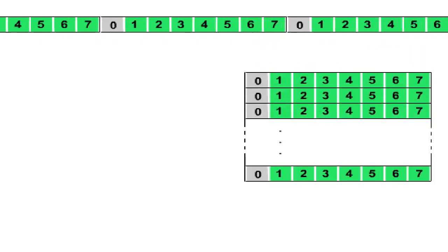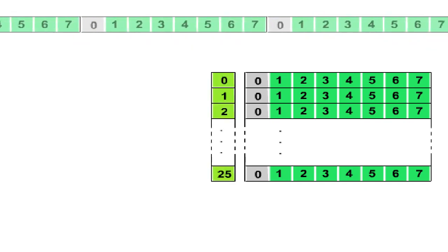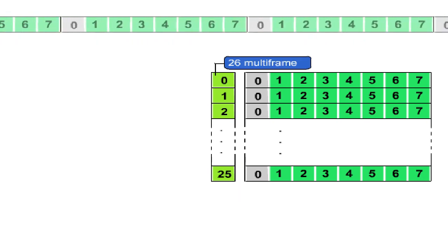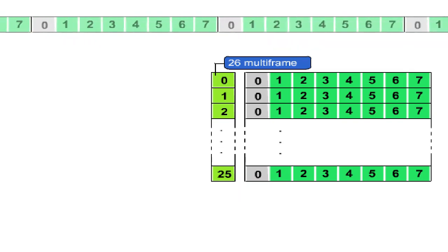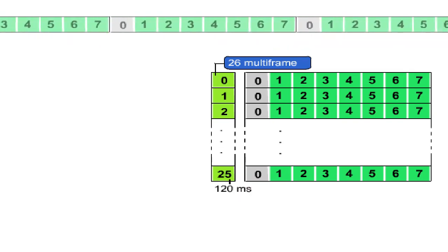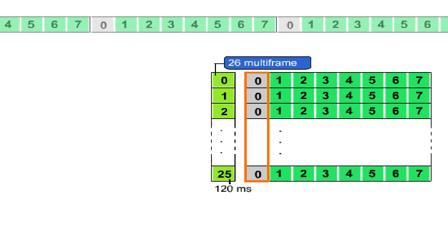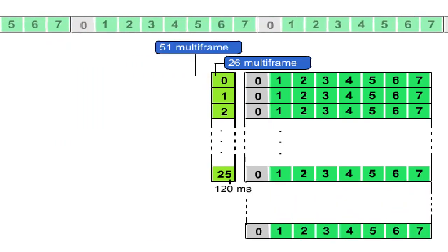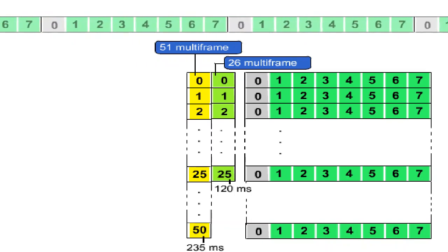Traffic channels, that is, time slots 0 to 7 in a basic TRX configuration, contain their information organized in 26 TDMA periods of time known as a multi-frame. This is 26 times 4.62 milliseconds, in other words 120 milliseconds long. Signaling information, normally provided in time slot 0, is organized in 51 TDMA periods of 4.62 milliseconds each, which makes 235 milliseconds altogether.